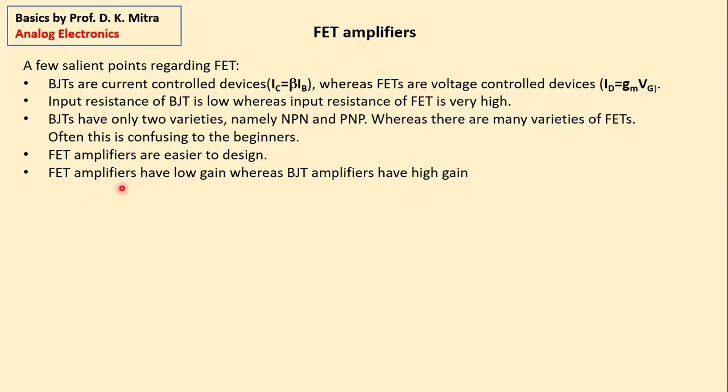One more point: FET amplifiers have very low voltage gain, whereas BJT amplifiers have high gain. So if you want a signal to be amplified, then a BJT is better than a FET. Then the question comes, why are FET amplifiers required at all? We shall reply to those questions one by one.